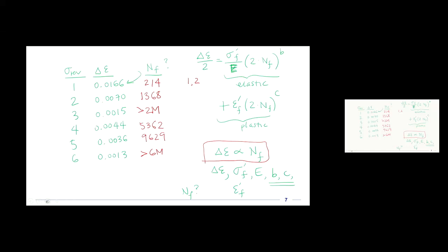And so then what we do is we calculate how much damage we get in one block. The amount of damage we get in one block is 1, because we only have one of these in each block, divided by that number. So 1 divided by that number, right? We just take the inverse. So this one's like 0.00, I'm going to keep 2 digits here, 7.